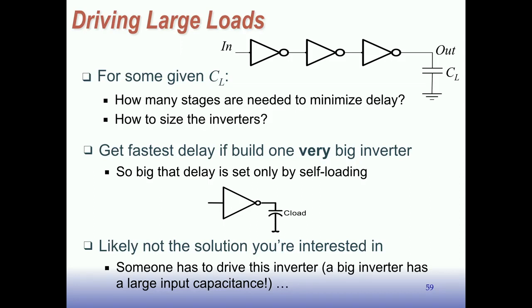By the way, I think of this kind of as impedance matching, if you've seen this in other problems in engineering. It's kind of like in a trumpet. At the end of the horn of a trumpet, it doesn't just end the pipe there. The pipe flares out. This is to create a better impedance match, or a better match between the pressure wave inside the trumpet and the outside world. If the end of the trumpet ended without flaring out, it would generate very little sound because a lot of it would just get reflected back into the horn.